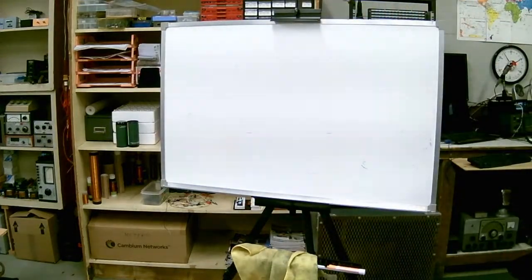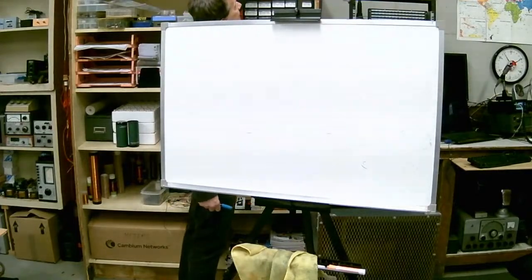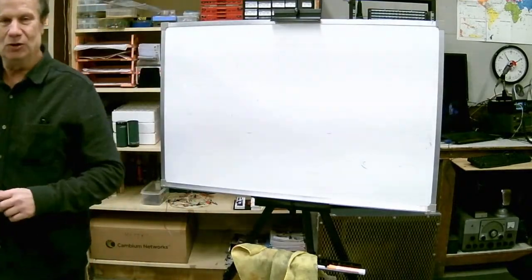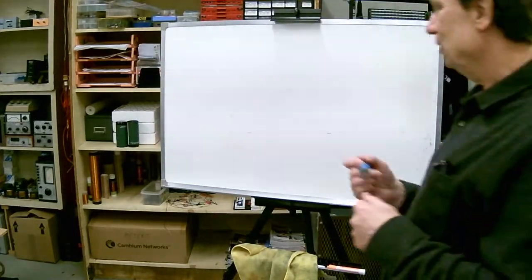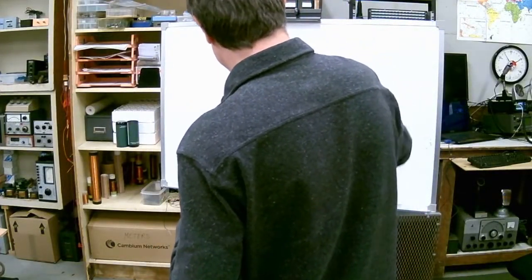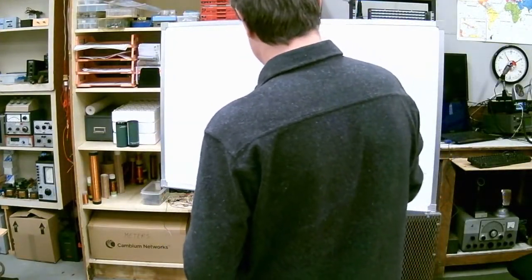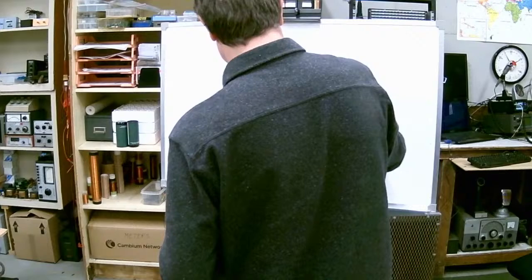And then one final class of antennas is actually 2 subclasses: loop antennas, like this guy here. There are large loop antennas and small loop antennas. The small loop antennas are usually used for direction finding. You want to know where a signal is coming from. A loop antenna like that has a radiation pattern which is actually null.